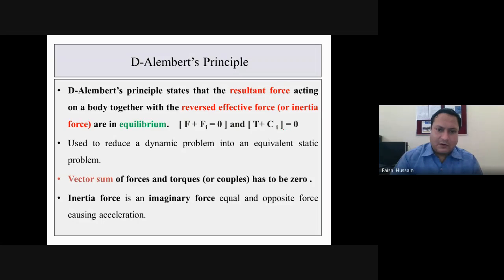And basically what I was discussing, this D'Alembert principle is used to reduce the dynamic problem into an equivalent static problem. That's why this D'Alembert principle is used. So in this D'Alembert principle, you will see that inertia force plays a very important role. In every equation, you will see the inertia force.